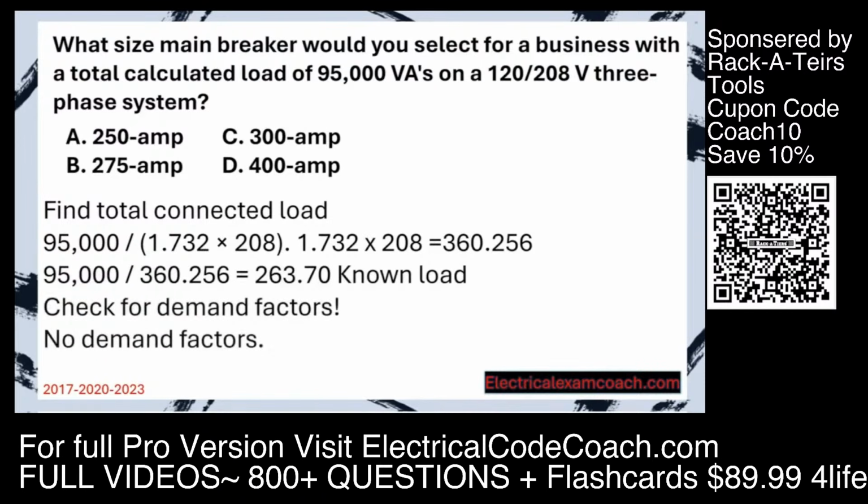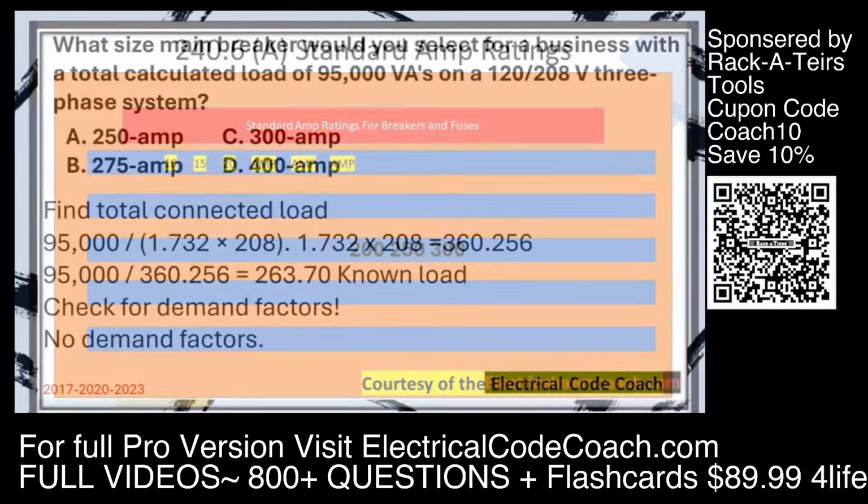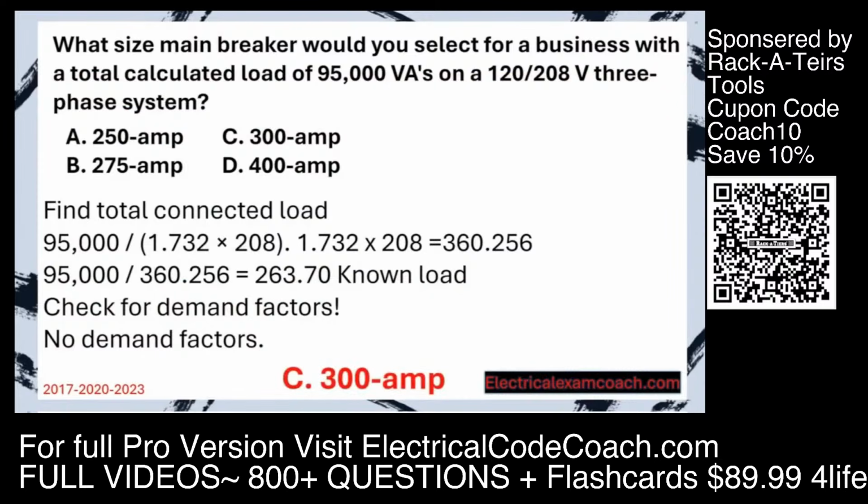There are no more demand factors, so we head to table 240.6(A) and choose the next standard size. And this is where the beauty happens. We're going to now put this on a 300 amp breaker. Instead of, like in the previous question, a 400 amp, meaning that we'd have to have larger wire in the previous question, which may lead us to have larger pipe, which we may end up with a larger cost of overall project.